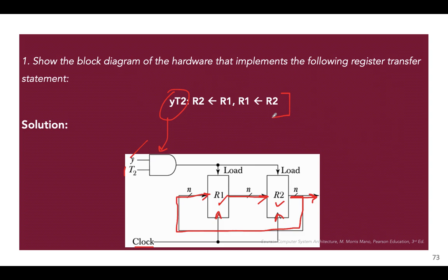Simple enough. First, identify the main components, which were the two registers, and see which of those registers are the receiving registers. Both of them are the receiving registers, so both of them have to get the clock. And then you need the control circuit. So the control circuit is given to you. You just have to use the appropriate logic gate, and then you're all set, right? This will control the loading of both the registers. Or you draw the appropriate circuits, you complete it, and that's it.